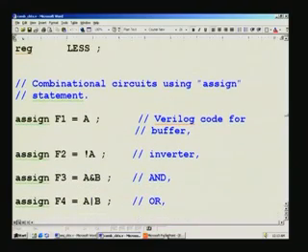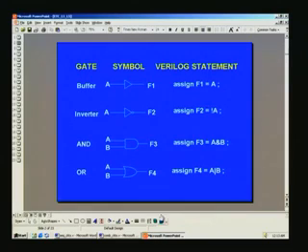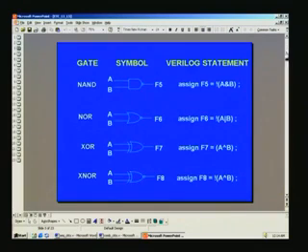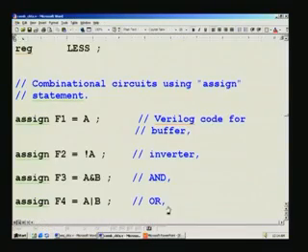So to start with, we had covered earlier how to implement a buffer using an assign statement, precisely that is what we have put here, the statements appear here. So that is what is appearing here as it is. That is why we said before that we will deal only with the core of the statements first, so that you get a quick grasp of those fundas, and then go on to more details which we have already seen here, namely identification of module, and then how to put it together, then IOs, and then declaration of wire and reg.